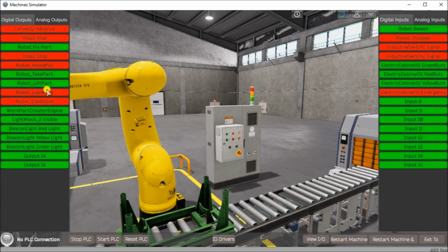Now, the third step of our EasyPLC Robotic Cell is to develop a logical sequence of operation. Now, a flowchart or sequence table is used to fully understand the process that needs to be controlled. So this process would be in conjunction with all the other inputs and outputs. So what has to happen when, and it has to answer questions like what happens when electrical power or air is lost? What happens when inputs and outputs fail? And do we need redundancy?